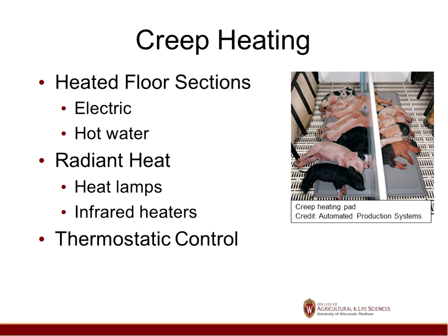Creep heating was about 11% of our cost, and I often get people saying, is there anything I can do to reduce the cost of those heating lamps I'm using? Typically you can't do a whole lot, but I'm going to show you a couple of options here. Many creep heaters will either have a spot in the floor where they have the heating elements inside the concrete, or this is an example of a heating pad that's electrically heated that you can put on a floor. So they can be electrical or hot water. The other thing we use is heat lamps or radiant heaters. The biggest thing here is to have them thermostatically controlled, so we're not overheating or underheating.